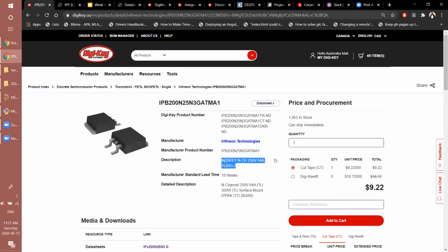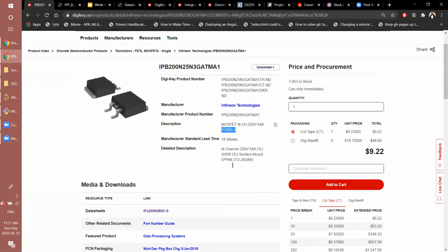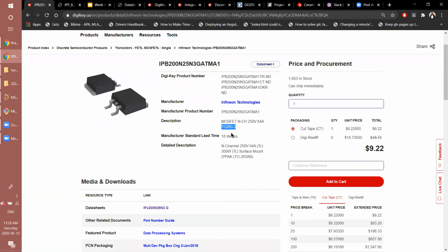If you're doing that, don't include the packaging, because it will really limit your search results, and we don't care about the packaging unless it's QFN, which means it doesn't have leads coming out. You'll find there are a lot of packaging names you're probably not familiar with, but if it has an N in it, it usually has the pads underneath the main body, which is hard for rework.